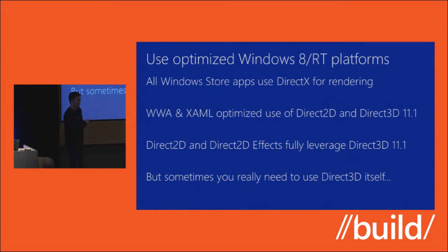Once you start talking about XAML, XAML is, again, fully optimized, uses Direct3D 11.1, and it uses Direct2D. Now we're talking about interoperable graphics, where with XAML, you can actually target XAML for your UI. You can use the swap chain background panel for doing underlying 3D rendering. You can use Surface Image Source for providing content to specific entries in the actual scene graph in XAML.